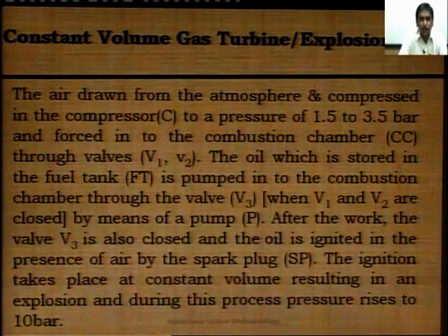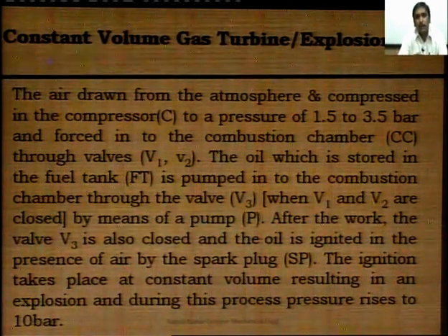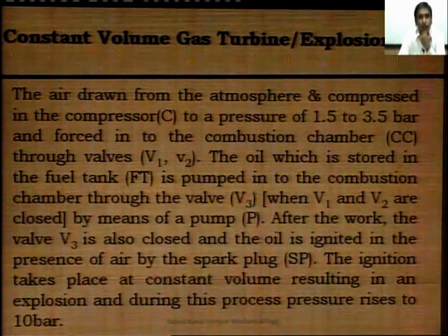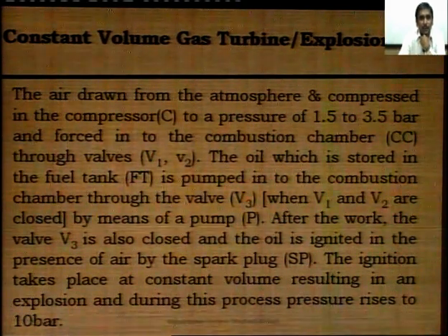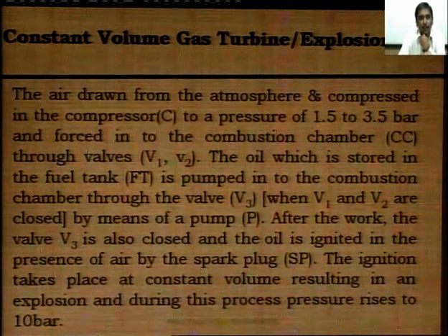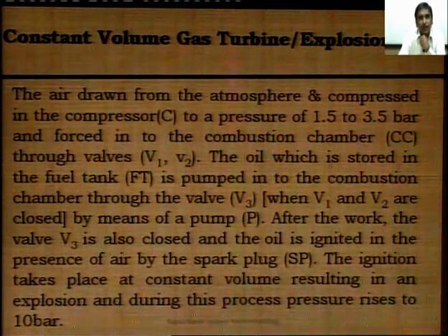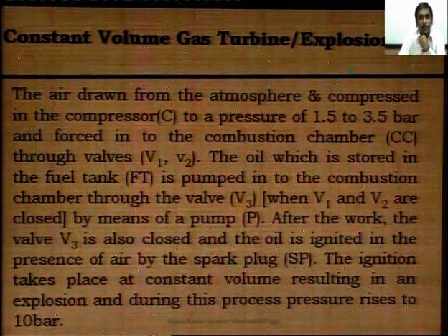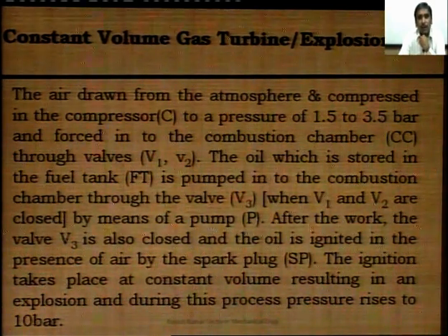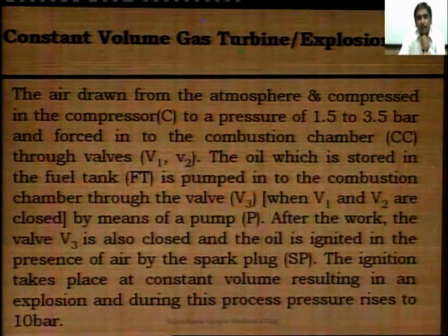After that, the valve V3 is also closed and the oil is ignited in the presence of air by spark plug SP. The ignition takes place at constant volume resulting in an explosion, and during this process pressure rises